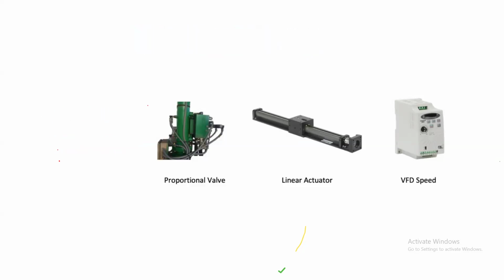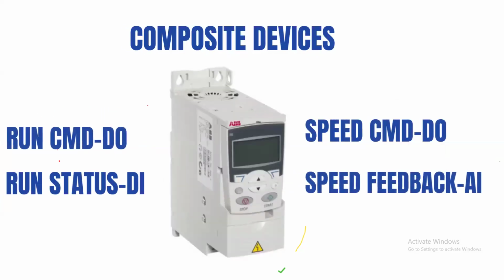Same thing for the VFD as well. There are devices that have composites. They are composite devices, I call them. So if you go to an interview and they ask whether the VFD is a digital input, or is it analog, the best answer is to say that it's a combination of everything. So let me say, this one I need to edit. This is an analog output actually.